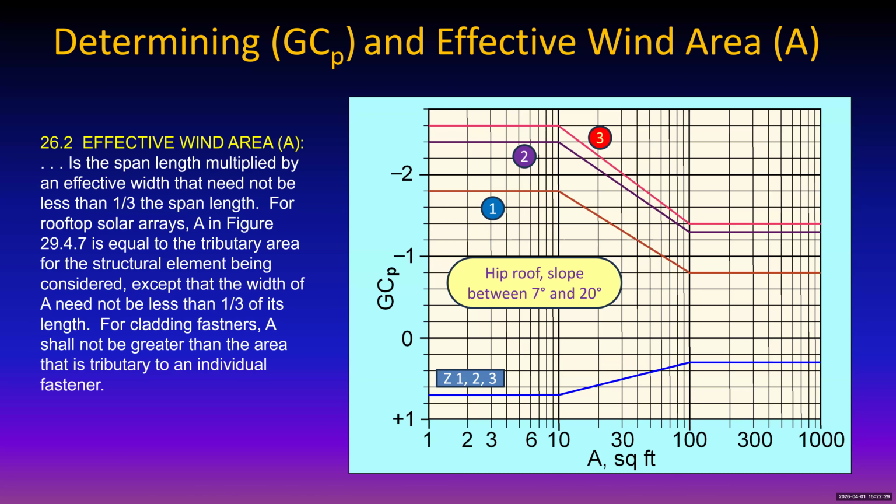For the final pressures in each roof zone, we have to multiply the 16.6 by the GCP factors for the zones. So wait a minute, if the GCP is big, that's kind of like a concentrating thing. Let's see. Well, zone 1, multiplying by the GCPs for zone 1, you get 9.96 downward and 24.9 upward. In zone 3, you get 38.18 pounds per square foot upward.